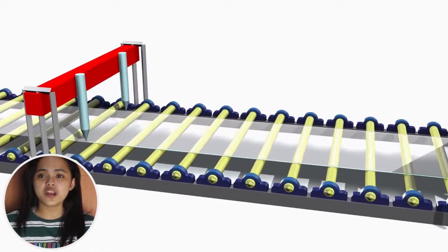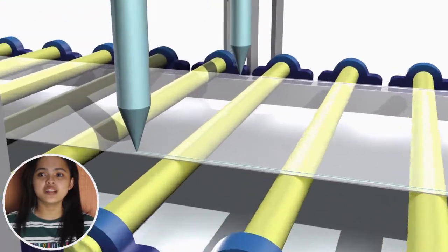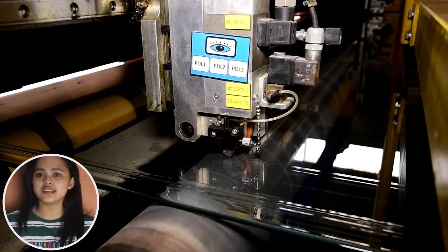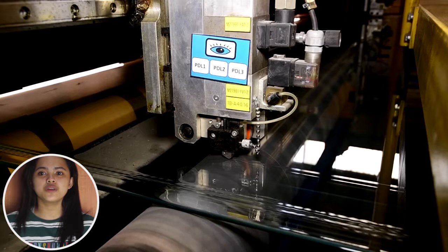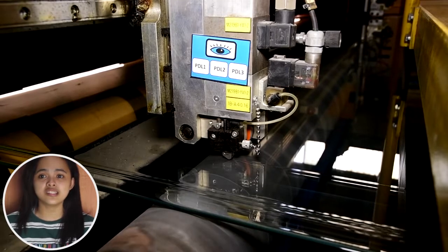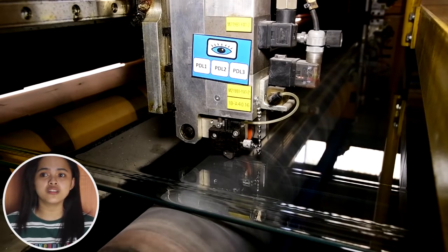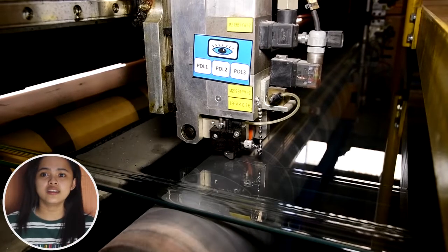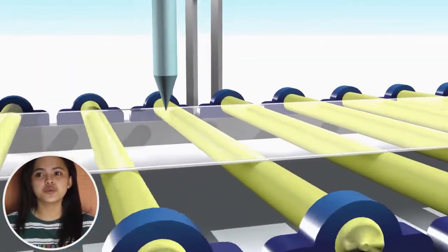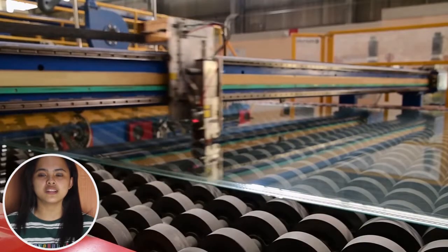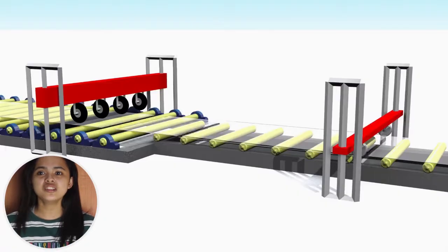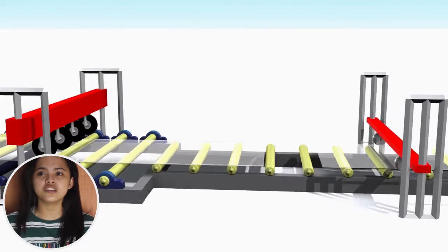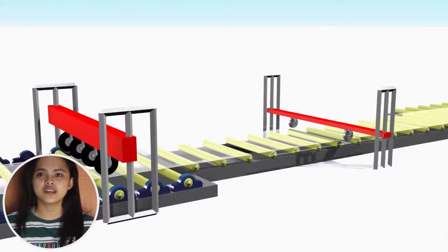The longitudinal stripes are made by a diamond wheel that creates surface defects on the glass. This prepares the ribbon for the subsequent cuts of its edges, thereby removing the top roll marks and obtaining the net width. Then, the transversal stripes will determine the length of the glass plates. In the breakage area, the continuous ribbon is interrupted to form glass plates.